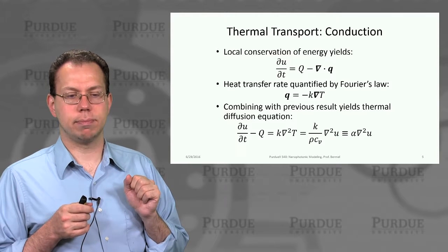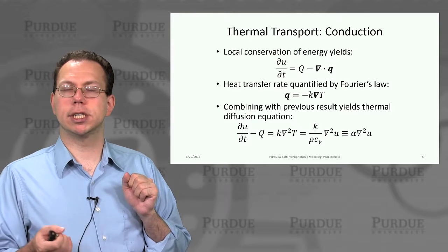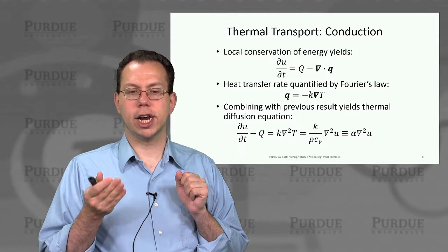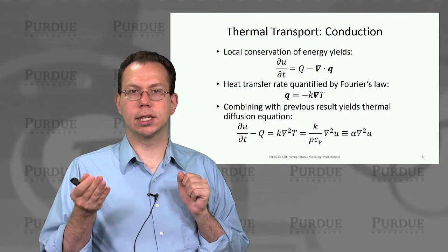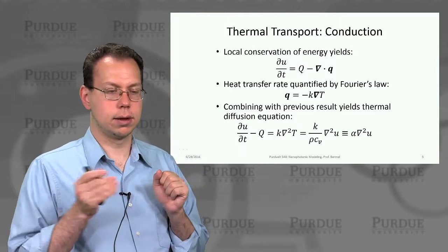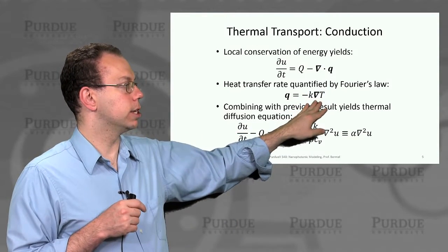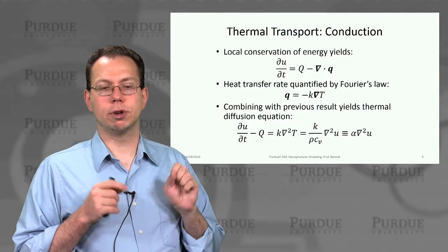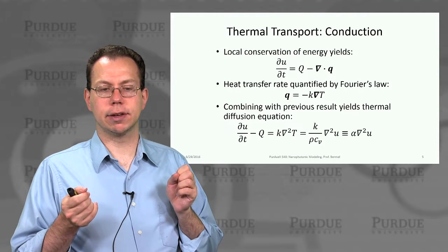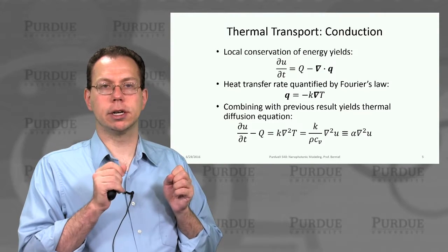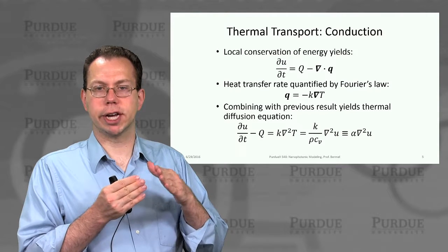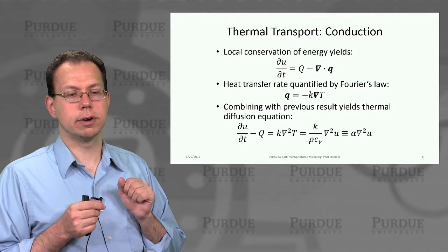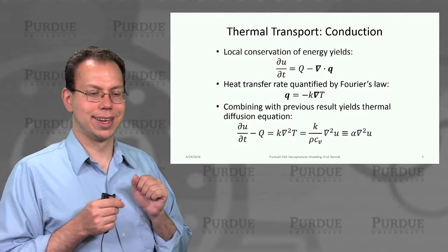And so Fourier's law basically tells us that the rate at which heat flows in equals the negative gradient of temperature times this thermal conduction coefficient, which is called K. And so this K here is material specific, of course, and sometimes there can be an additional thermal resistance, which is like the inverse of the K, coming from other sources, like maybe you don't have perfect contact with that surface, like the hot stove, for example. Actually, hopefully you don't, right? So then that can actually decrease your K.